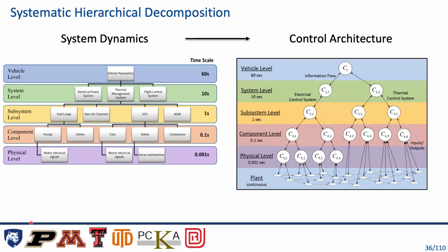Well, why not have a control strategy that just exactly mirrors that dynamic or the structure of those dynamics. So that was our intent: to design hierarchical control strategies where these upper level controllers are thinking about just the slowest timescales of your system. They update at relatively slow rates, but they're looking far into the future to plan out what the system should be doing over, let's say, several hours. And then as you work your way down your hierarchy, each controller is responsible for a smaller and smaller portion of the system, is making decisions more quickly, and is looking over a shorter prediction horizon.